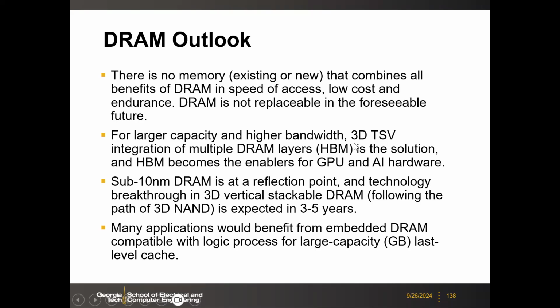And if you look at the H100, each H100 has 6 HBM stacks, and in total you have 96 gigabytes. One GPU card is not enough to hold the 1 terabyte model. That's why you need more than 10 H100s to run this 1 terabyte large language model.